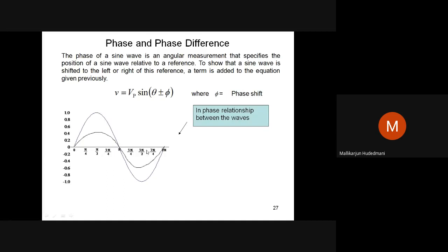Later, pi to 2 pi, it will run into the negative cycle. Likewise, any alternating quantity, when omega t equals 0, 10, 20, 30, like that, in either degree representation or in omega t directly as a radians representation, I can project it as a waveform. Suppose I have a quantity sine theta or sine omega t alone, it would look like this. There could be another representation, where apart from the omega t or theta, you have plus or minus some arbitrary angle phi mentioned.